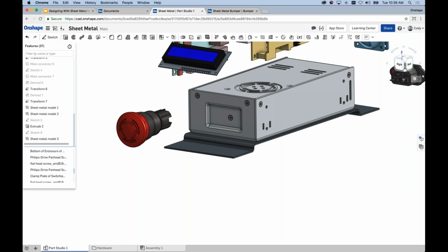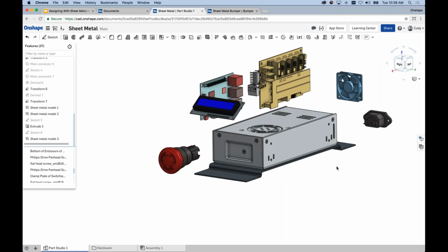Can you use the developer API for Onshape to create or modify sheet metal parts for automation? I don't see why not. Yeah. In this case, if you look at this example, the entire thing was driven by that initial block, and it's very easy for me to edit that initial block and update sheet metal parts accordingly. And it's really how it'd be built. But the developer API does allow you to access and change values.